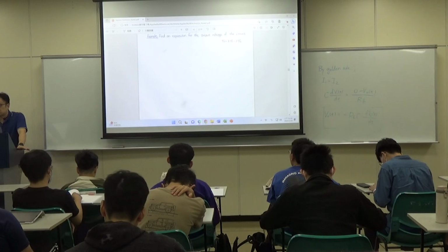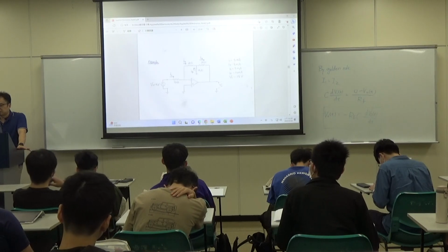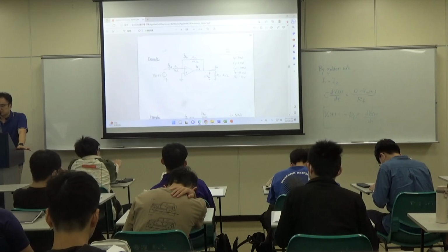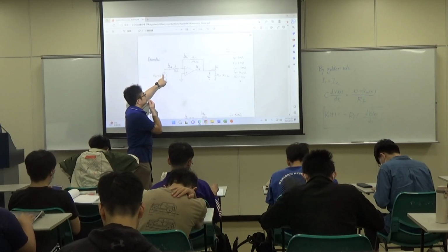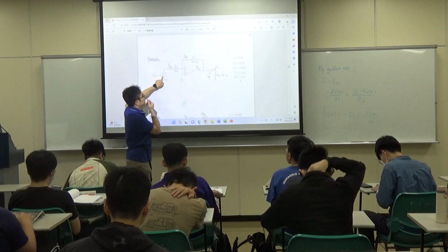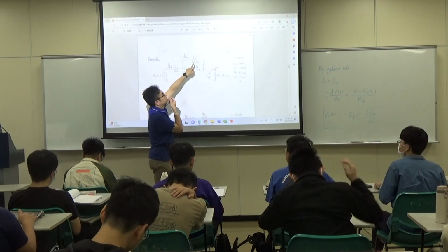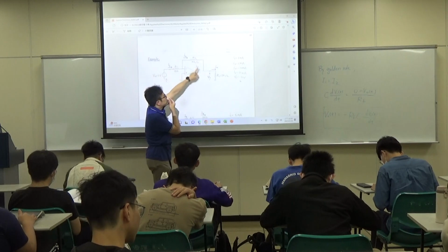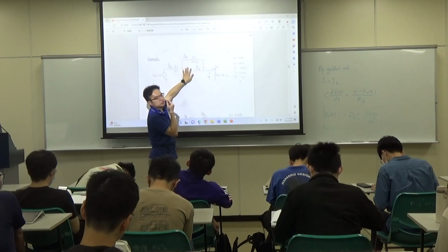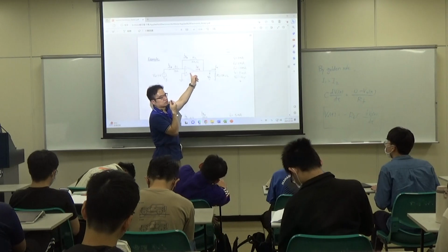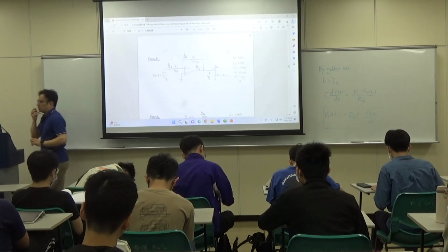So this is how you design the circuit. One more type of problem is this. This is an inverting amplifier. Because you connect the voltage to the inverting side, R1 is the input resistance and R2 is the output feedback resistance. You may be asked to calculate I1, I2, IO, IX, and VO. Please try it on your own. I already gave you the answer. This is an inverting amplifier, and you should be able to calculate it by using the golden rule.